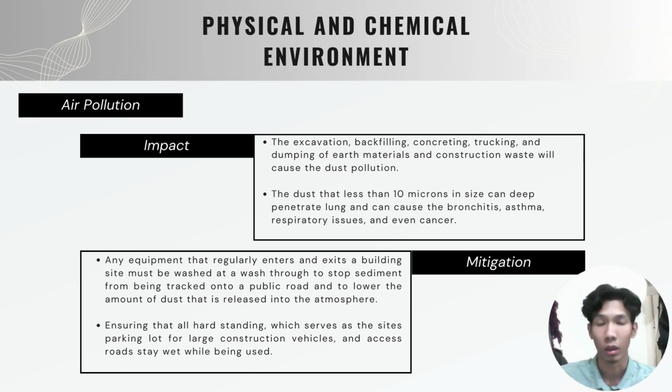For the mitigation, any equipment that regularly enters and exits a building site must be washed at a wash-through to stop sediment from being tracked onto a public road and to lower the amount of dust that is released into the atmosphere. And next is ensuring that all hard standing, which serves as the site's parking lot for large construction vehicles and access roads, stays wet while being used.